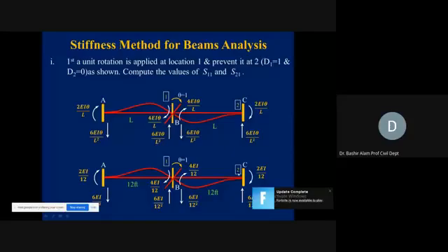Now coming to the BC span. In the BC span, again, rotation here at B. So this is our near end. So the moment produced here will be 4EI divided by 12. Again, you see this curved arrow head is in the clockwise direction showing the rotation. Remember, 4EI divided by 12, where 12 is L, is from the BC span.